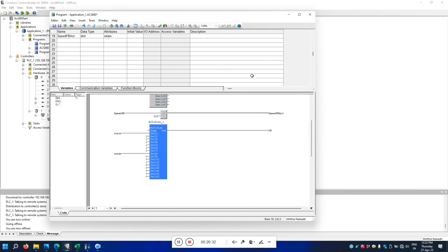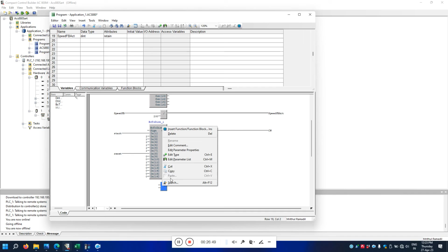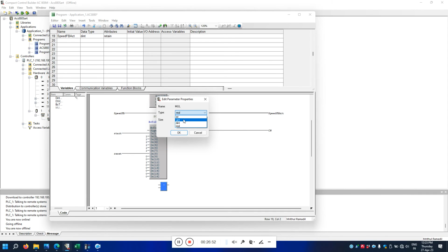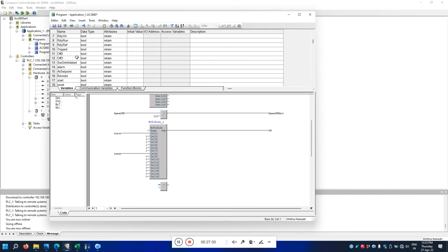Okay, similarly let's give the speed reference. So speed reference, again, if I'm going to send it in percentage, I need to multiply by 200, change to double integer. So the speed reference, where's the speed reference?